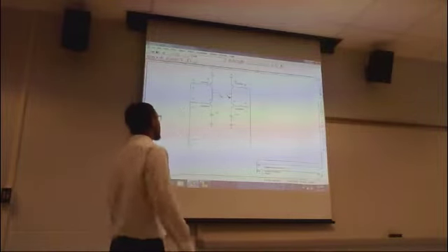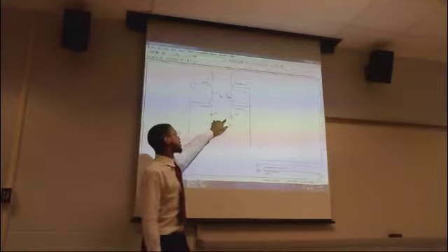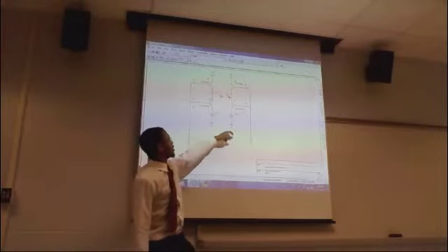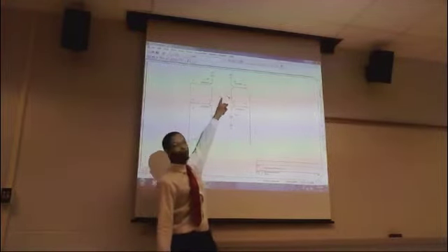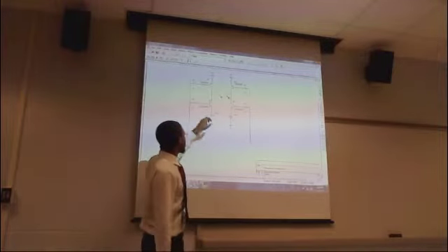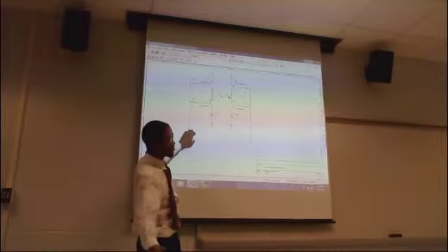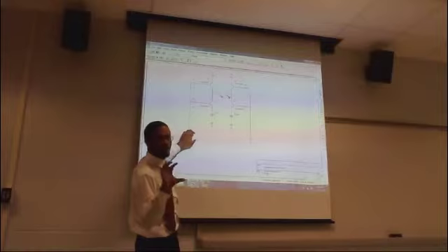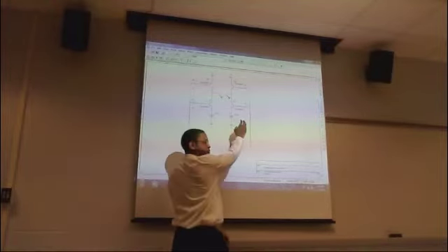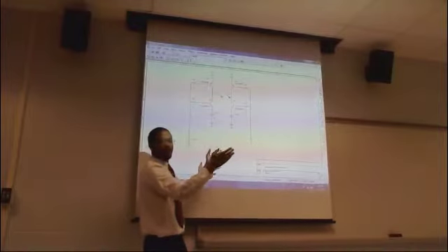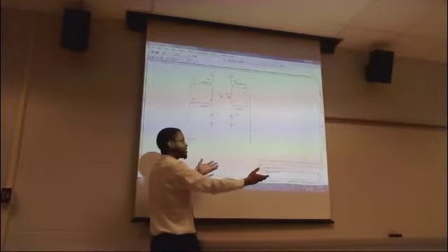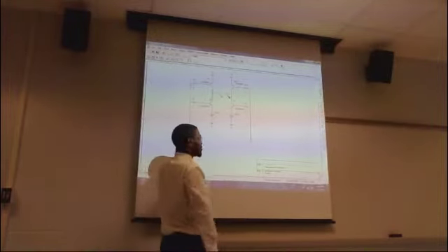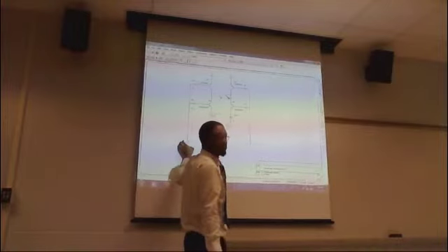And basically for each part, this is supposed to represent the 5-volt inputs that will go into the motor controller itself. Green represents the front wheel, red represents the back wheel. And this right here represents the digital input that comes from the logic protection gate. Because of how the motor controller works, it has to be either 1 or 0 for the motor controller to actually turn on. If it's 1, 1, I was told the unit will probably blow up, and if it's 0, 0, it won't turn on at all. So it has to be essentially an exclusive OR gate.